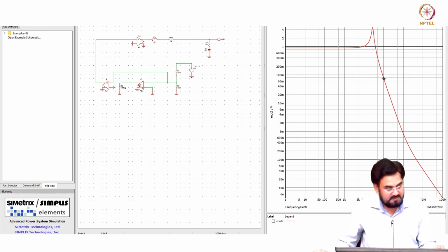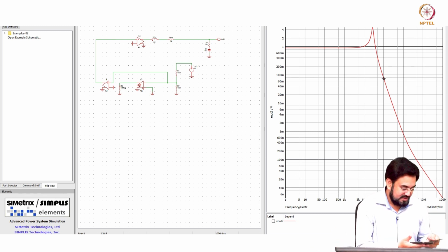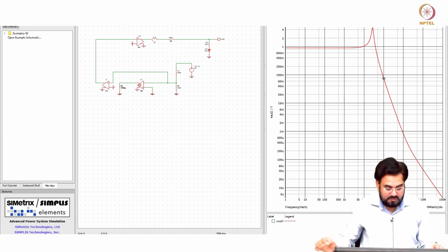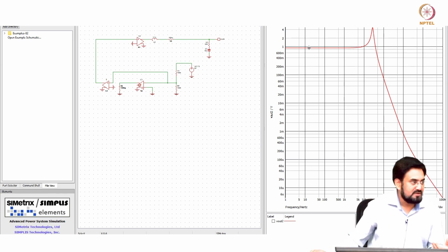Gain is 72 milli, which means the total gain we require is 1 over 72 milli. So, how much is that? 1 divided by 0.07, 14.2 roughly. Okay. So, 14.2 means GMR of this, I want to shift this whole thing to 14.2 times, correct, which means 0.9 into 14.2, you will get.